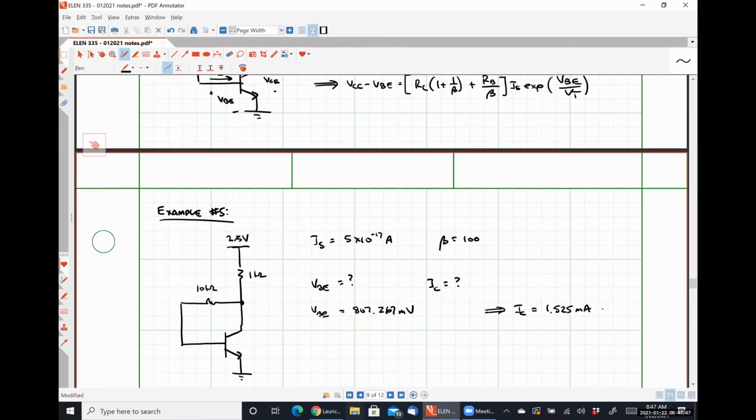Yeah, that makes sense, right? If the resistance RB increases, then the base current must decrease, right? That's just good old Ohm's law. If the base current decreases, the collector current decreases, which means VBE also has to be lower. It's just simple relationships like that. So that would be a good theory question I might ask you on an exam, right?